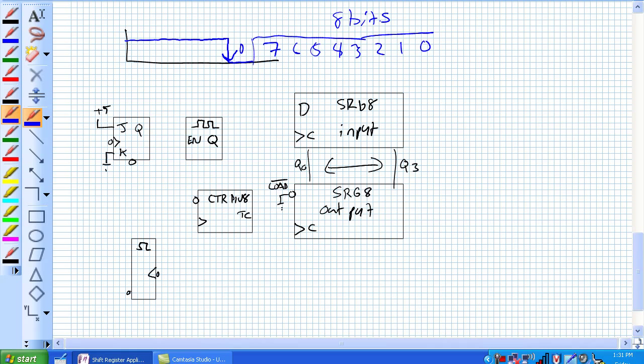And we know that it's 8 bits. That's the key to this thing here, is you know that you're expecting an 8-bit package. If you were expecting a 6-bit package or a 7-bit package, it would be totally different. But we know, this is one of those things. You're in the States. Normally, you would expect to be speaking English. If you're in Rome, you would normally be expecting to speak Italian. So it's the language already. And this language happens to be always high when no data is sent, a start bit of 0, 8 bits of whatever. Then you've got 2 guaranteed stop bits, 1 and 1.